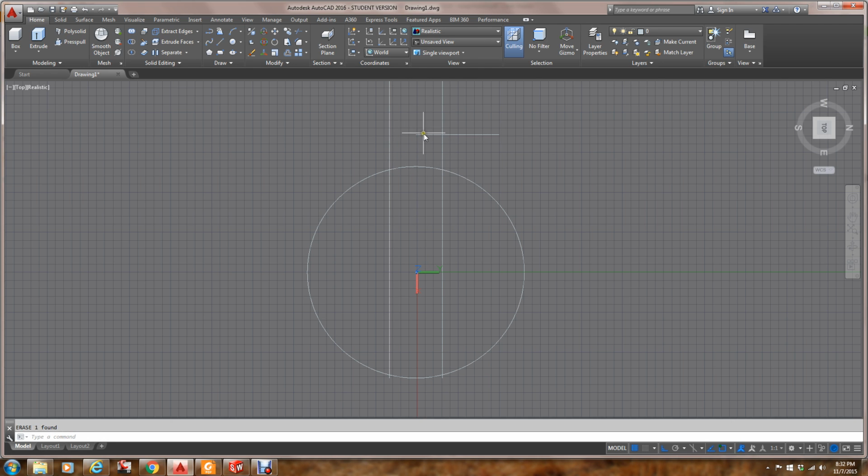And I need to clean up these corners, so I will just use fillet, and that should be right here. I don't want any radius. As you see, I've got a radius of 0 down here because I want it to be a square. So I go this line to this line, and now to repeat my same command, actually I'm not going to do that. I'm just going to go back up and hit fillet again, and I'm going to pick this line and this line. So I've got the little key out area, I've got the circle.